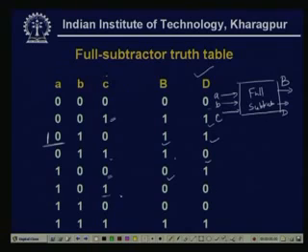So, that means actually 1 minus 1. So, difference is 0, borrow is 0. Now, 1 minus 1, borrow 0. So, simple, all are zeros, borrow 0 as well as difference 0. Here 1 minus 1, but one borrow is there. So, if it was 0, just like the previous case, as the borrow is 0, 1 minus 1, we know that difference is 0, borrow is 0.